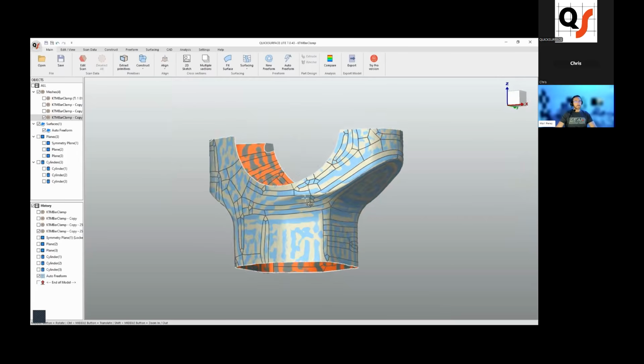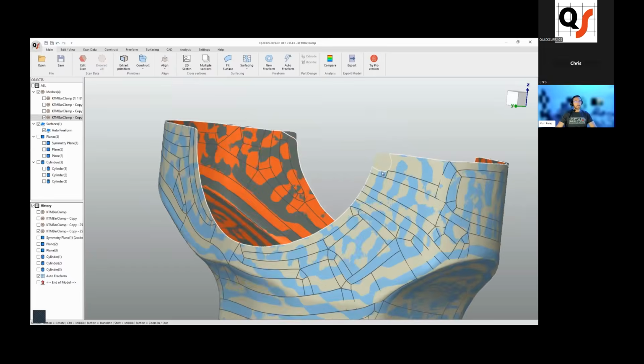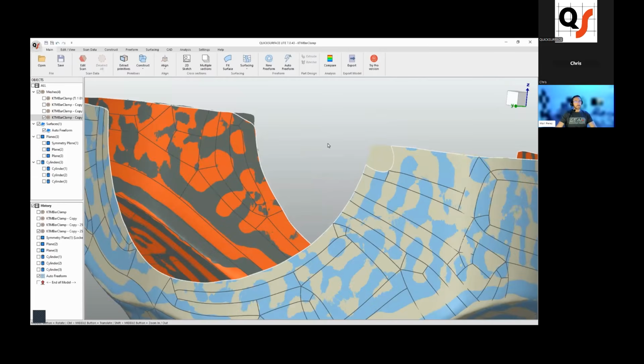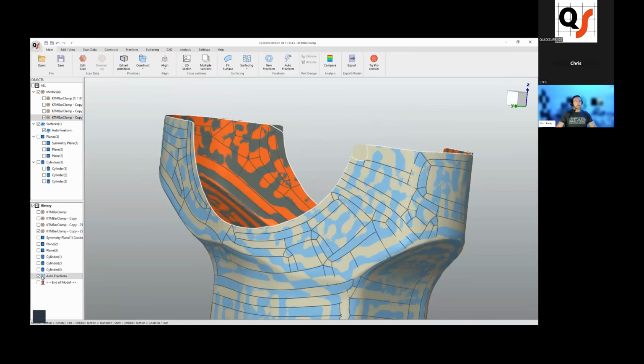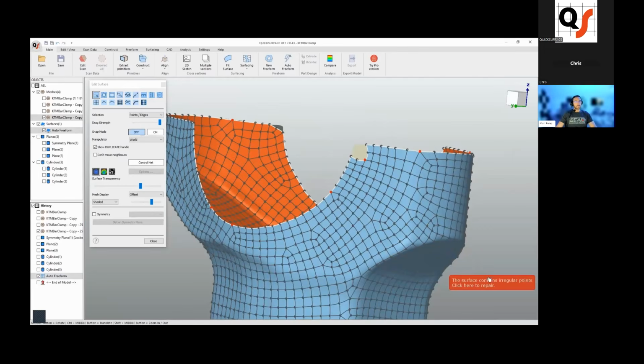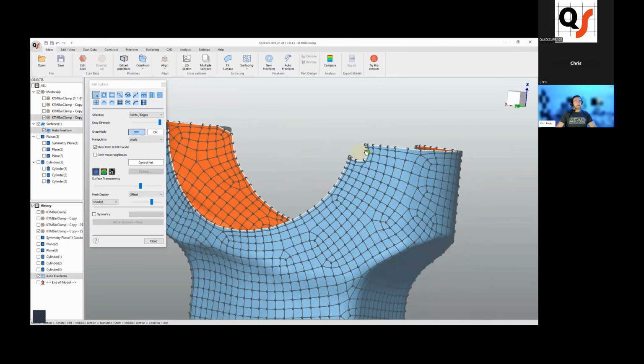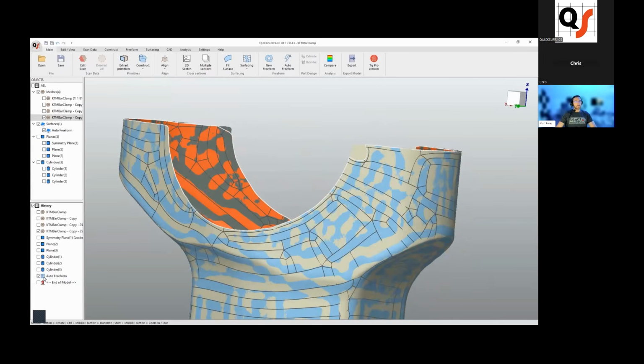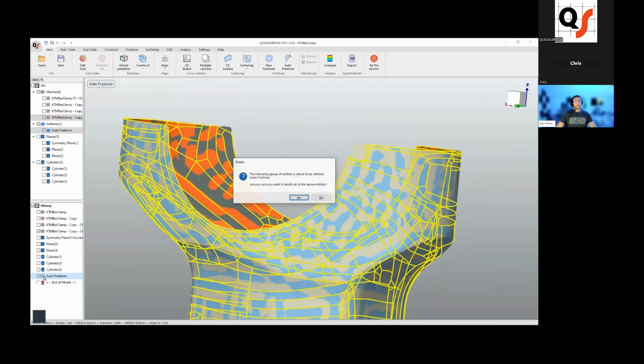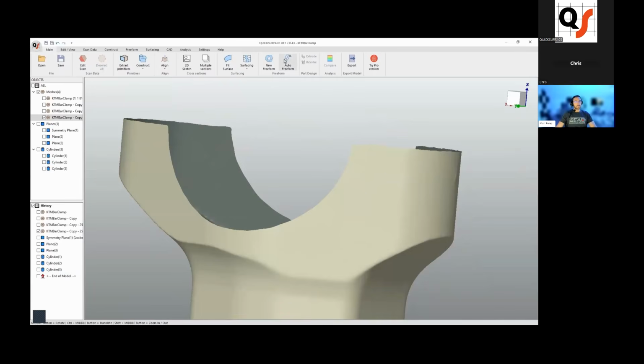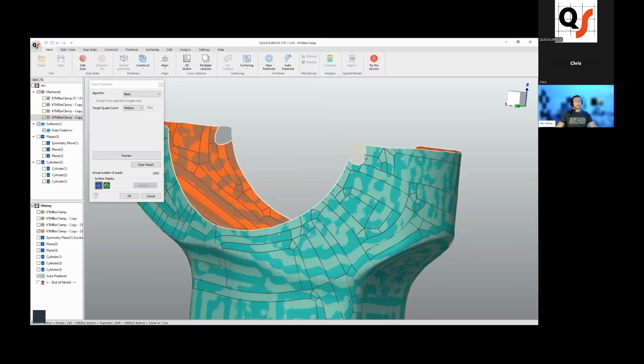All right, so now that we have this, you'll actually notice there's a big hole over here, or there's something going on with the boundary here. I'm going to double click on Auto-Freeform to edit. Any of these red dots, we're going to click. Those are regular points. I really don't like this, so I'm actually going to delete the Auto-Freeform, and I'm going to go back and do it again. I want to just take a look. Yeah, so that hole there, I really don't like it.